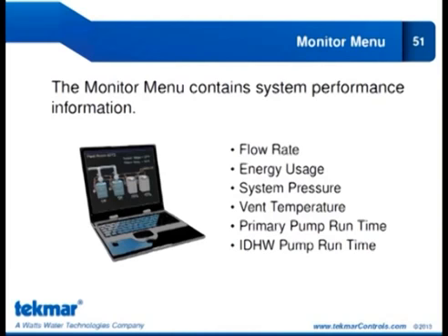One option I'd encourage you to consider there, or other reps to look at, is there are gauges and thermometers out there which are dual sensing. You have indication at the gauge or at the instrument, and then it also sends a 0 to 10 back. And so that's nice, because lots of times you'll have a system where you can't really look at the Tecmar control, for example, at the same time as look at the gauge. Yeah. Or you have a mechanic who's more familiar with looking at a gauge.